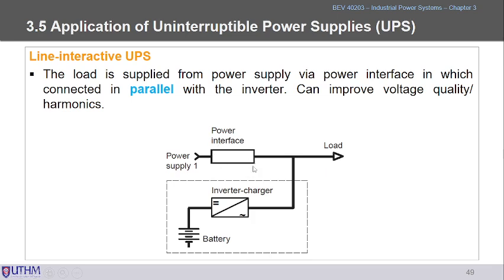It is not that severe. If the voltage quality condition is severe, we also cannot use the UPS to correct it. Rather we need to use other devices to correct the voltage. For example, we have the AVR, or we have the reactive power compensator to correct our severe voltage quality effect.